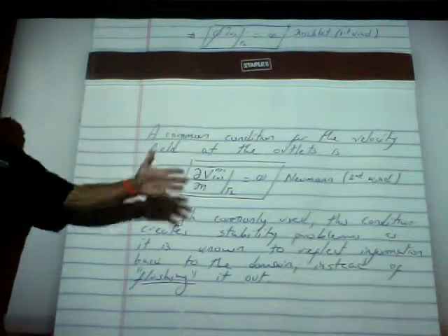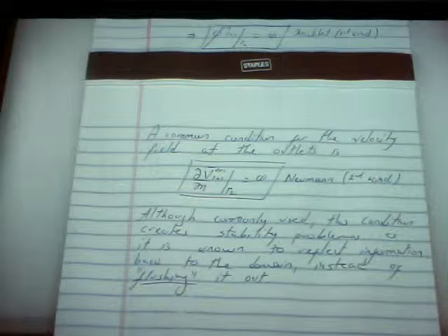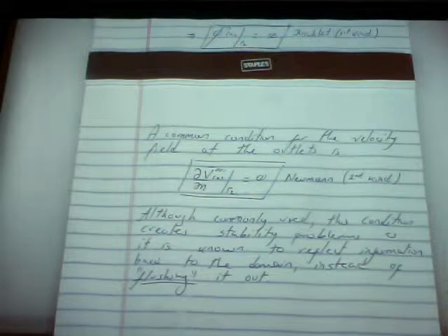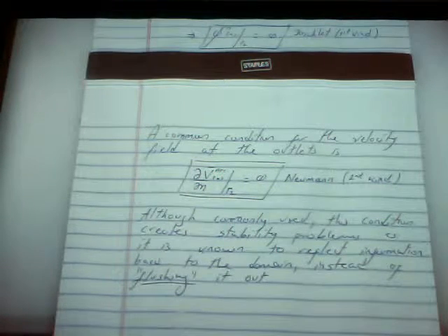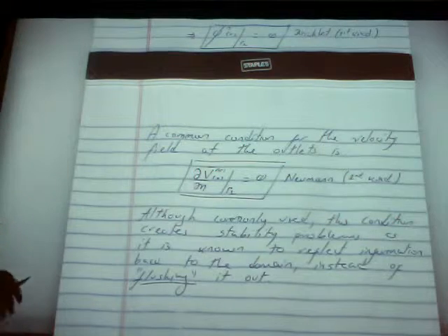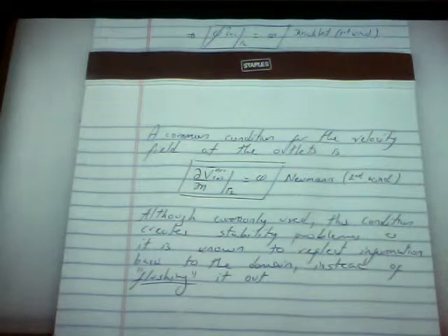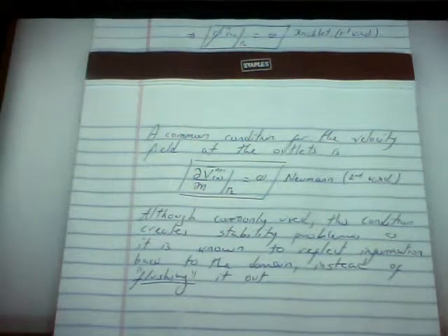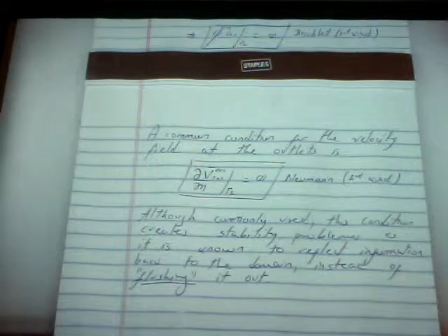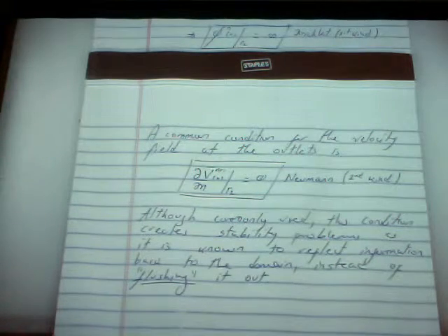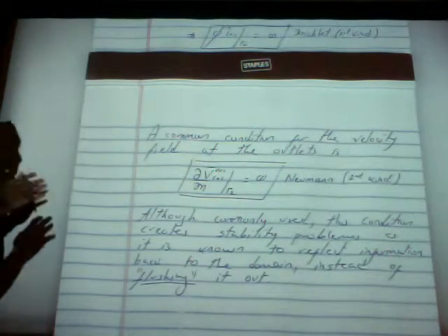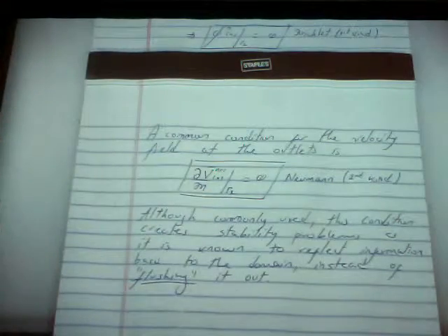It's a way of faking a condition for a fake boundary that doesn't exist. Remember, the outlet boundary doesn't really exist. It's just an open boundary that you say, well, things are going to flush out through there, but the fluid actually continues to flow somewhere. So what you want to do is make sure that everything goes out through the boundary. When you set something up like this, some of the things are bound to reflect.